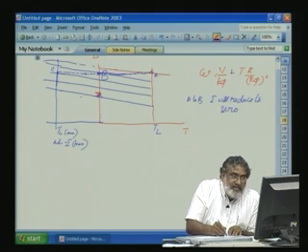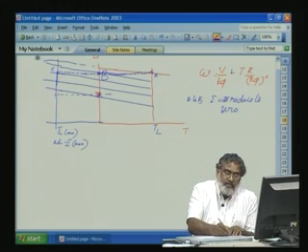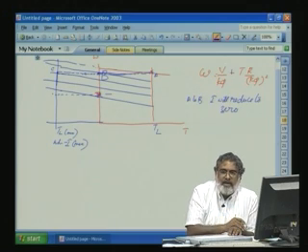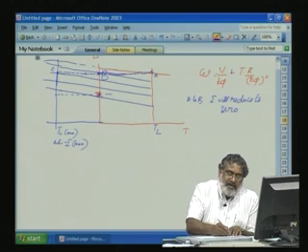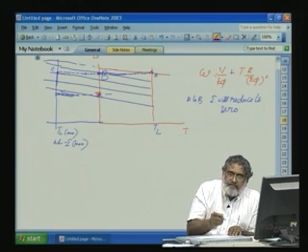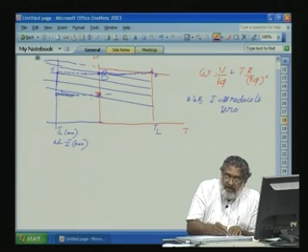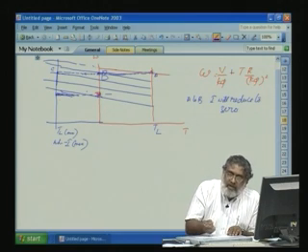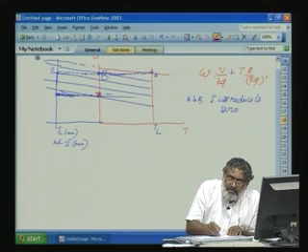Okay. Now, this is our rated speed. We want the next speed somewhere here. So, machine will come to this speed, slowly slowing down, regenerating. Okay. Now, speed has come to our rated speed. Here again we do not want the speed to go down. So, we will sense this, and the converter voltage will slowly increase. Slowly increase means these are the curves. The machine will slowly go from this region. So, the speed is constant. So, we are going in this direction. That means the regenerative power we are reducing. So, that way the regenerative negative torque slowly will reduce and quickly the system will come here.